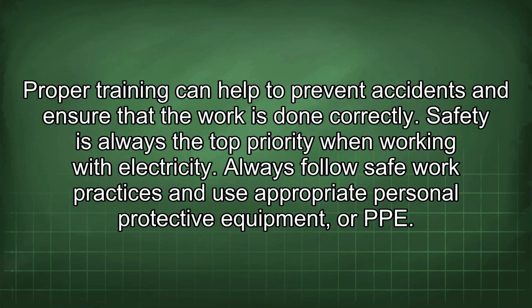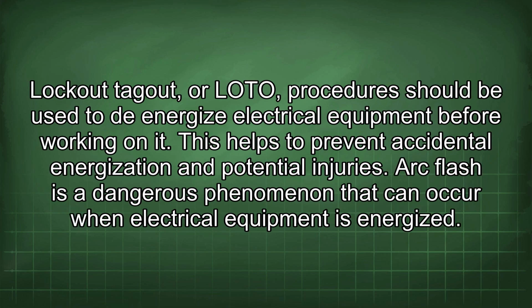Always follow safe work practices and use appropriate personal protective equipment, or PPE. Lockout, tagout, or LOTO procedures should be used to de-energize electrical equipment before working on it. This helps to prevent accidental energization and potential injuries.